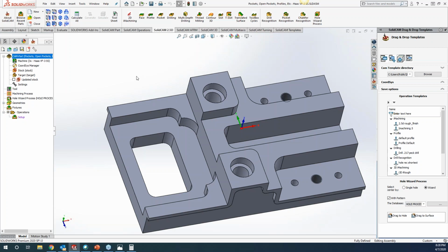When you get into the very brittle materials, using a climb cut would actually chip out the material. So the suggestion that we got from you guys is to give the operator the option to switch that over to conventional or climb cut. So now that option is in there for you.